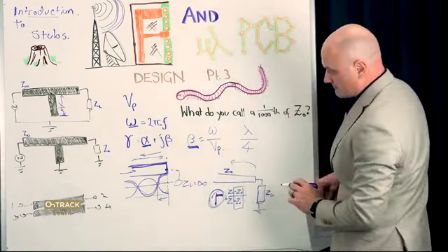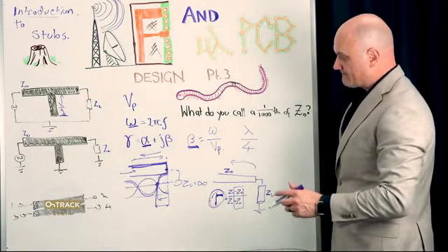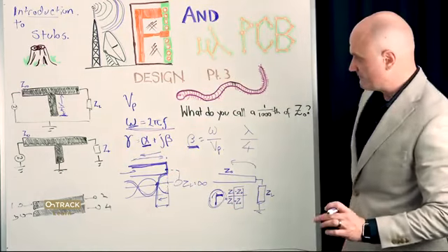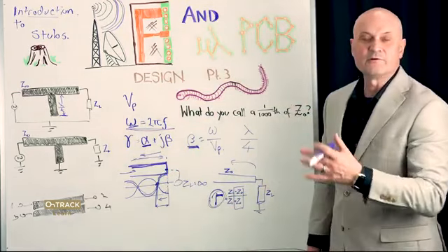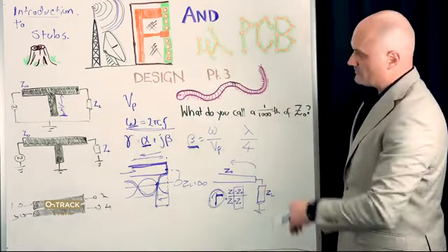Okay, so a quarter wave back from the open, we have a null, and the voltage is fixed at 0. So a quarter wavelength long piece of open circuited transmission line, which is called a stub, appears to be a dead short, but only at the frequency where it happens to be a quarter wavelength long, depending on all our other transmission line calculations, which we did in the previous episodes.